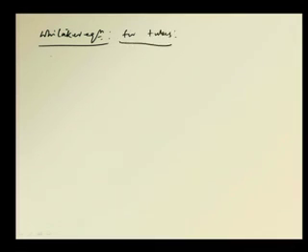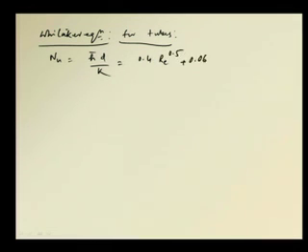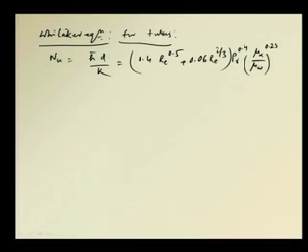Okay. So, Nusselt is equal to h bar, the average heat transfer coefficient, times D by k, and this is equal to 0.4 Re to the power 0.5 plus 0.06 Re to the power 2/3, times Prandtl to the power 0.4, times (mu infinity by mu w) to the power 0.25.